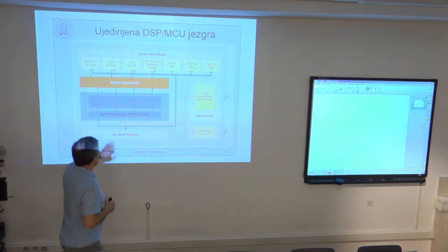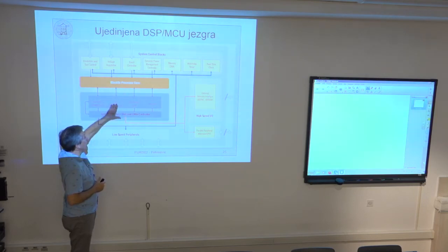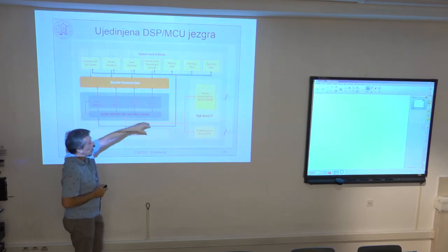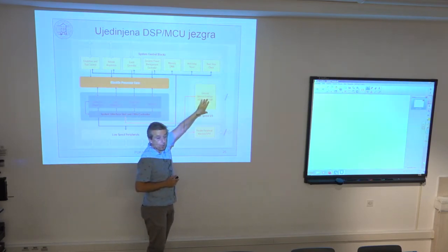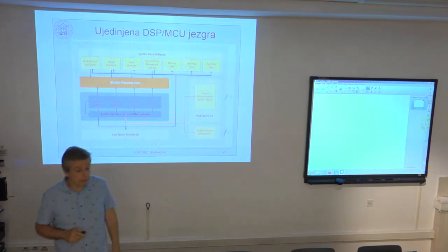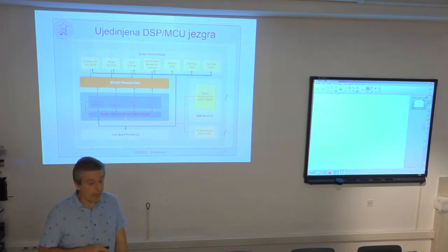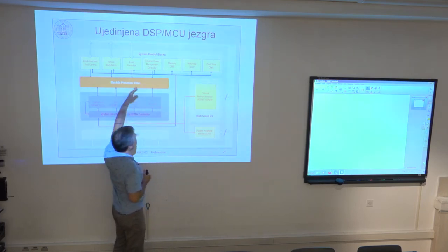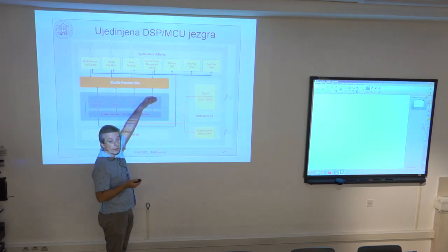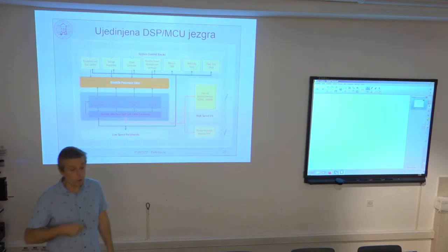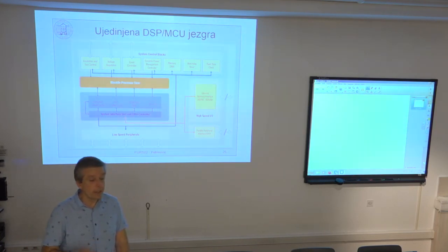And if I'm lucky, if this data value is already stored in this cache, it comes directly from here. I don't have to go into outside memory, external memory. So if it is not contained in cache, then I must activate this memory interface and really fetch the data from, for example, the dynamic synchronous RAM that's connected to this chip. And this here is much slower because this here operates on the full CPU core clock. This here takes several cycles to be able to address the data from memory, to fetch the data, and it is